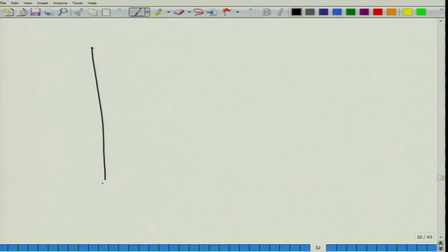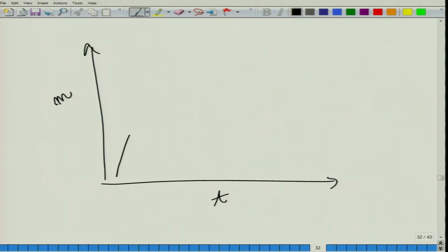But when you put your sample inside water and plot mass versus time, your sample is going to absorb water till it becomes fully saturated with water. So, when you put your sample inside water, you should take your measurements as soon as possible, otherwise your sample itself is changing with time.